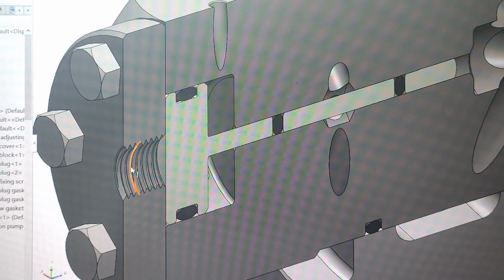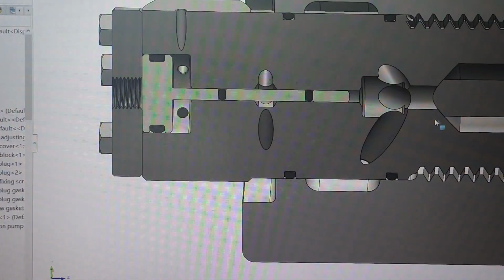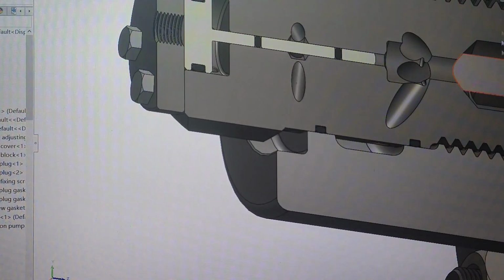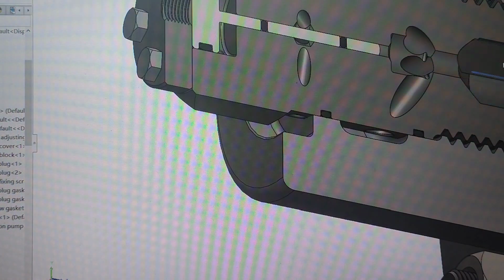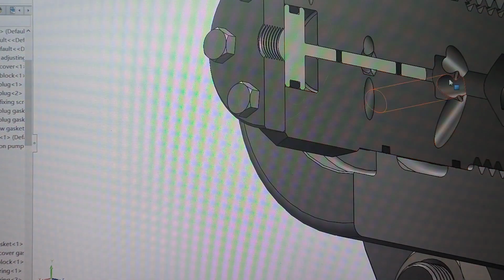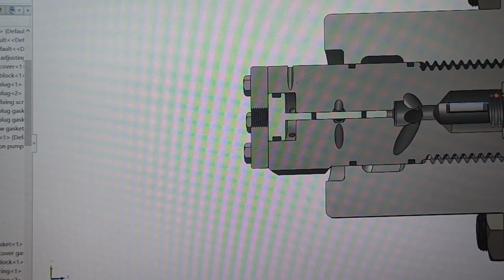Alright, so the high pressure air will activate this downward and will push down this valve. You can see actually here this is a small valve, but due to the angle I cut this model apart, it's not quite easy to see that. This is a valve. Alright, a spring loaded closed valve under normal condition.